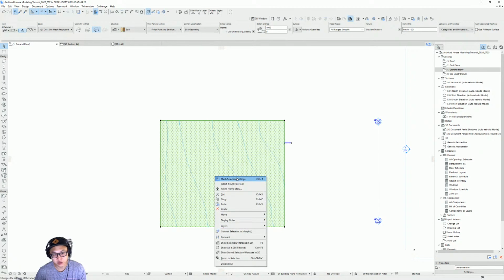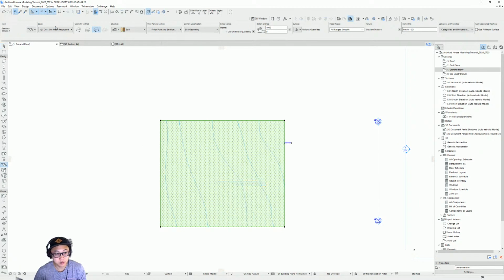And now you have to activate the mesh tool. So make sure that you selected the mesh, it will appear here. And if you press spacebar, it will activate this little icon here, just like a magic wand. And you just have to mouse over one of the lines that you just created, click on it, press OK, and it will create points on your mesh following the line you just created. And you do that for all of them. One little trick that I like to do to speed up my process is to click in between two lines, so it will create points on both sides.